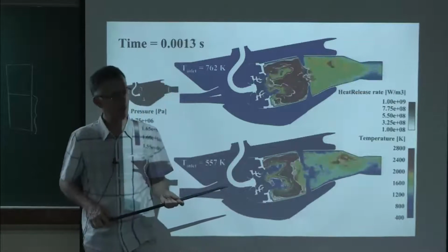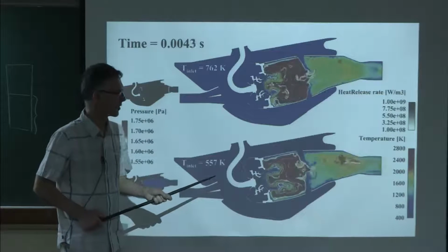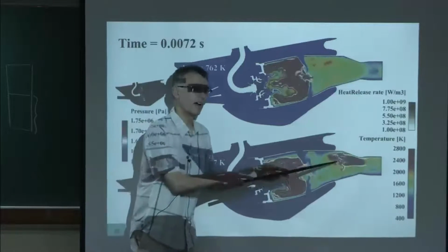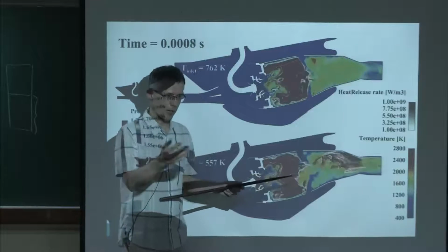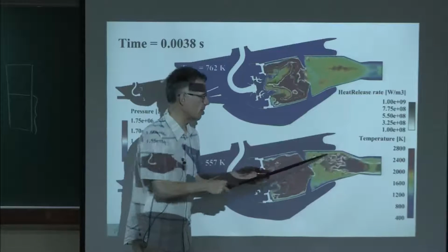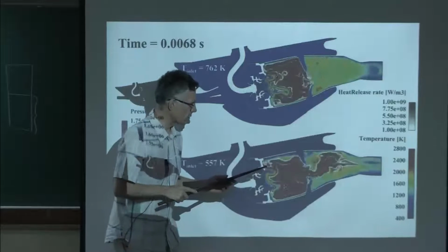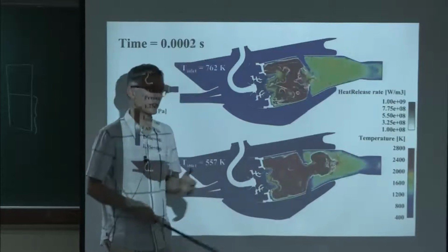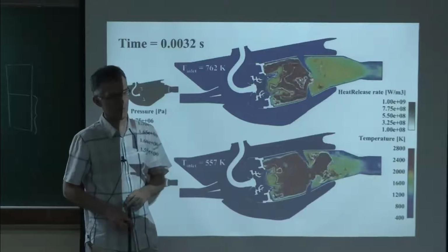This frequency of oscillation is not the acoustic one. It does not scale, exactly, because you're going up at the sound speed, but you're going down at the convection speed. So the lowest frequency here for the acoustics must be 600, and this mode is at 200 because you're going down at the convective speed. This is the key of the problem. You must introduce some convection phenomenon to account for the frequency you see. Otherwise, everything acoustic is at much higher frequencies.